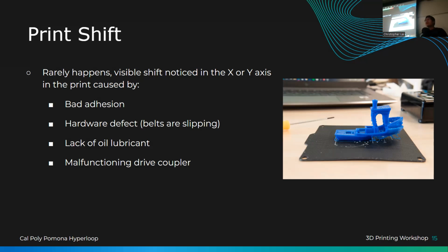Now, saying a heater uses a lot of electricity, I will say that the normal breaker can handle about 15 amps. A heater can draw 5 amps. Each printer can draw around 1 amp or so. So, let's do the math. For me, I think there were 10 printers active at the time, not 16. Three of the printers completely died from the power outage during the print. I had to scrap them.